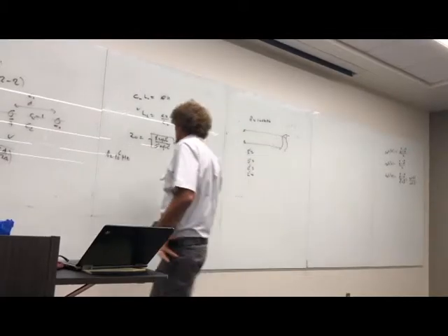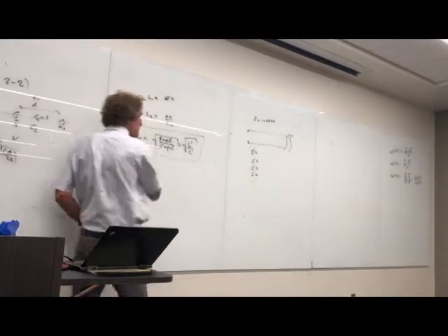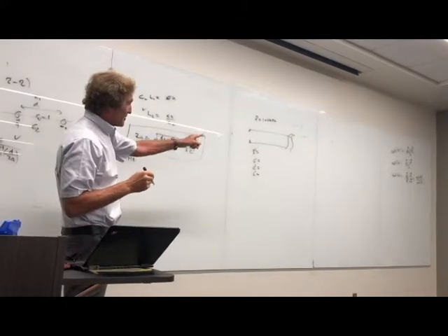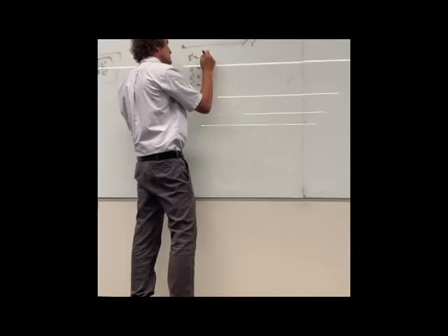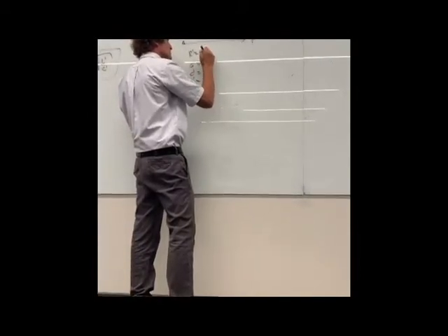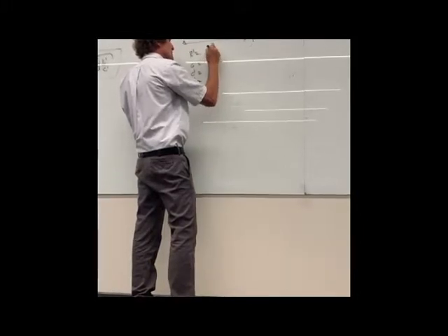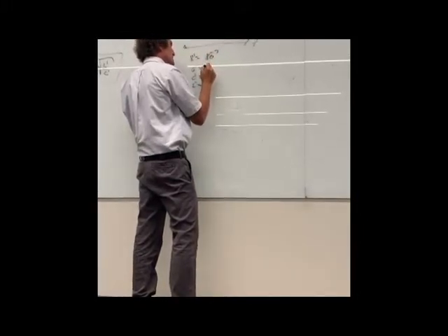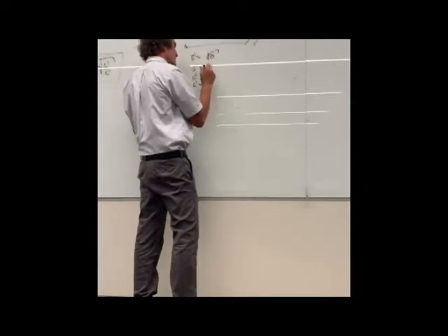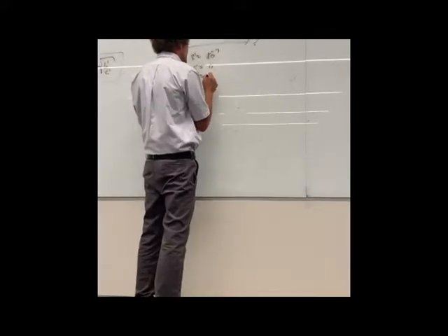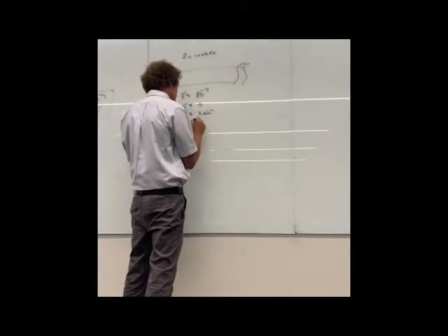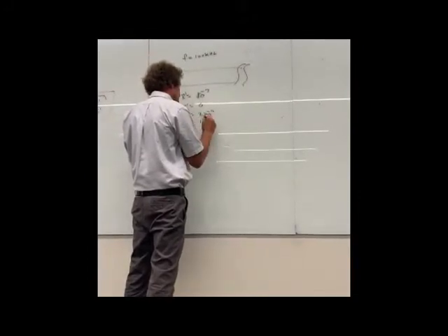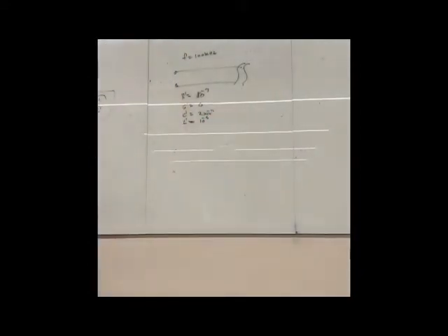All right, well, here is Z naught in a nutshell. It's given. We have the RG, you might as well just tell me what they are. R is what? R is 1 milliohm per meter. That's 10 to the minus third. Go ahead, G. G is 0. Okay. C, 2 picofarads per meter, 2 times 10 to the minus 12. Go ahead, and L. 1 times 10 to the minus 6. All right, so they're always per unit meter parameters.